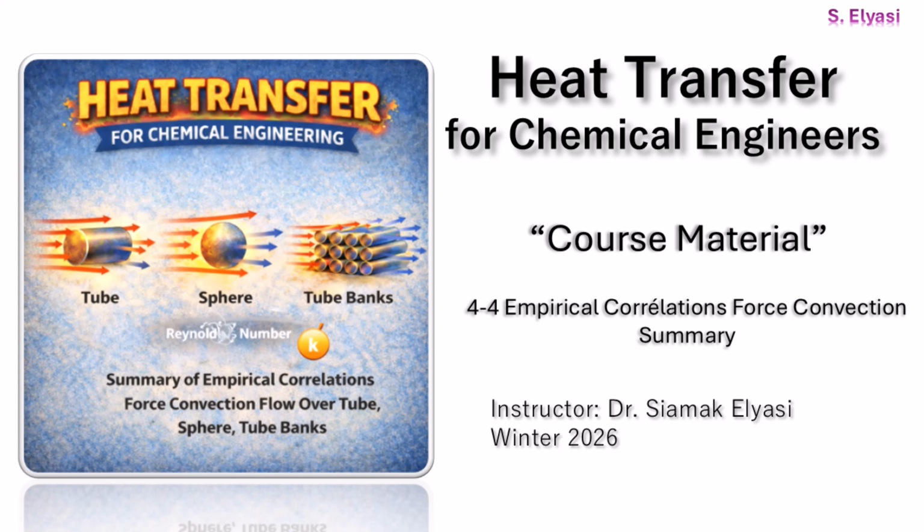First up, let's talk about flow inside a tube. You can't just use one equation for everything, right? If your flow is fast and turbulent, you're going to use a robust formula, like the Dittus-Boelter equations. But if it's slow and smooth, what we call laminar flow, that's a whole different story, and it needs its own set of formulas. Even the entrance of the pipe has its own special correction.